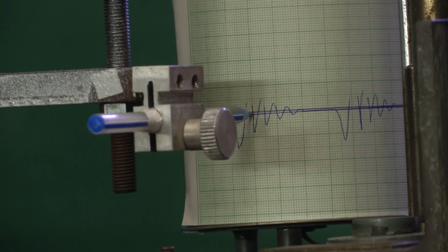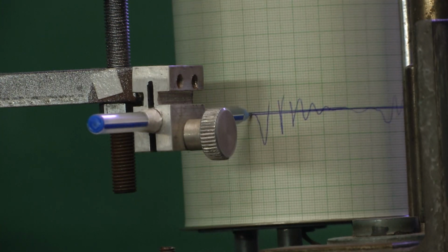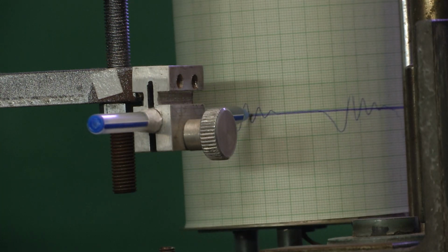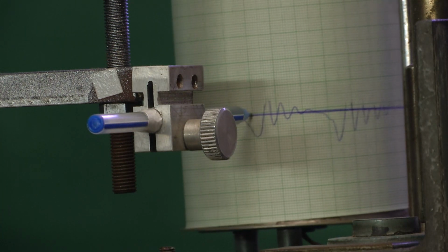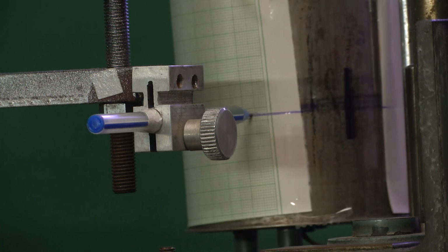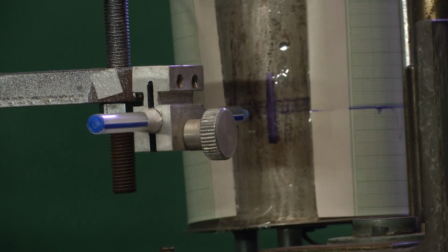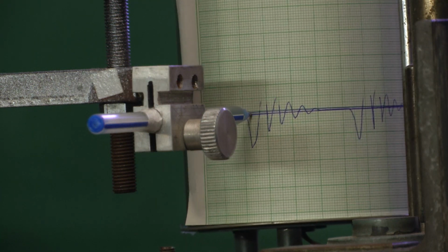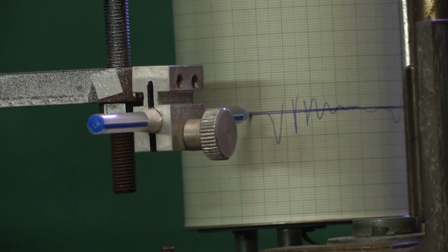So, we will provide you these graphical measurements traced out on the graph paper, and from that you have to find the amplitudes and take an appropriate number of cycles as is feasible from the short data, and then calculate the value of zeta, the equivalent viscous damping factor.